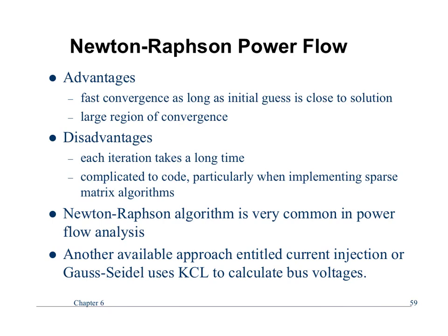As a matter of fact, I think we looked at PowerWorld for Windows a few days ago, and the only method they had available for load flow was Newton's method. It used to be that there were 2 or 3 other methods that you would see. Now this particular software application only had Newton's method. Gauss-Seidel is another method. We'll talk about it, but we won't really get into it because nobody uses it unless Newton-Raphson doesn't converge. But it's another way to solve nonlinear equations.